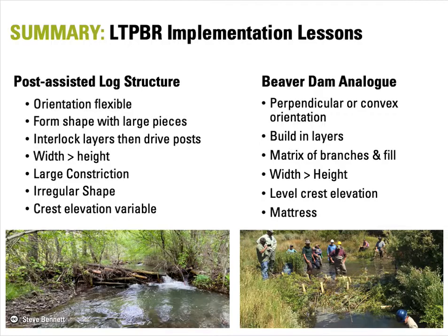Really, really try to get that matrix of branches and fill and keep interlocking. Again, keep a nice wide base, wider than the height, and you want a level crest elevation and a nice mattress to dissipate that energy as the water comes over the structure. And if you do all those things and you build these structures, you're going to be happy. And thanks very much.